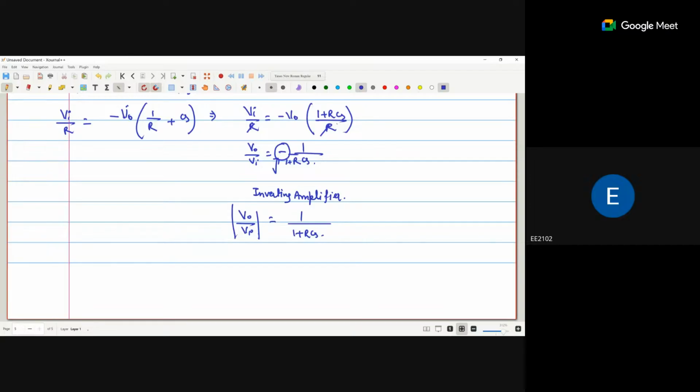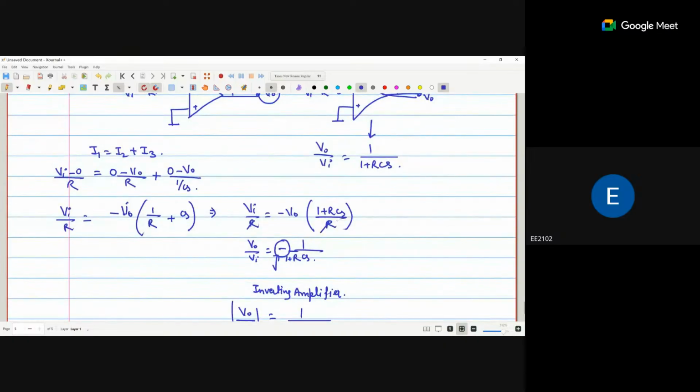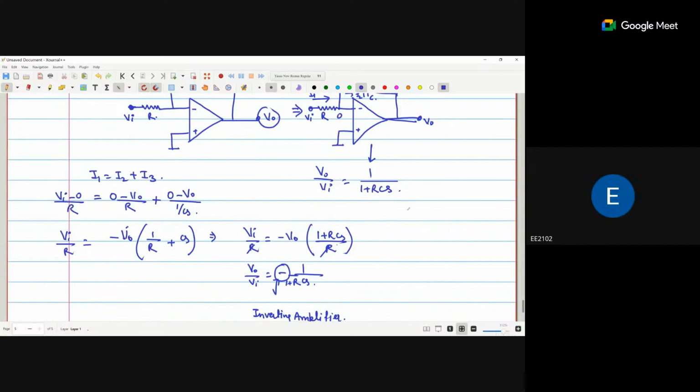Okay, to overcome this phase shift, what do we do? We just require one more operational amplifier here, with negative sign, positive sign grounded. This is the resistor. Again, in the feedback we are using the values R and R. So here we are getting this particular minus. Now what is the gain of this one?